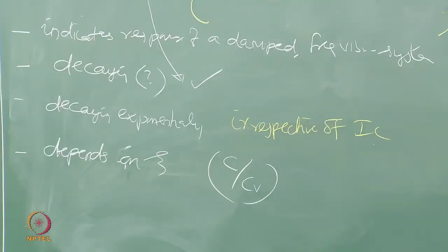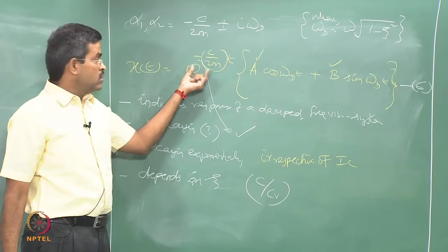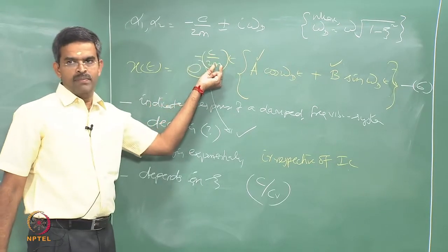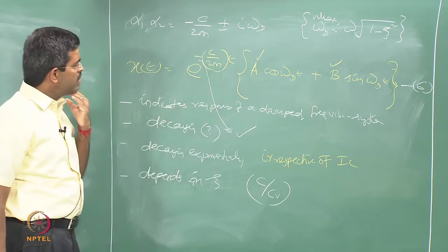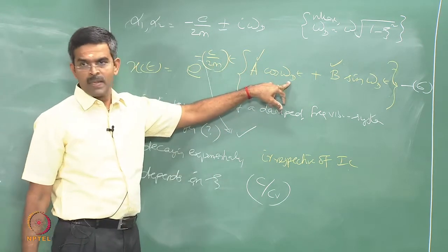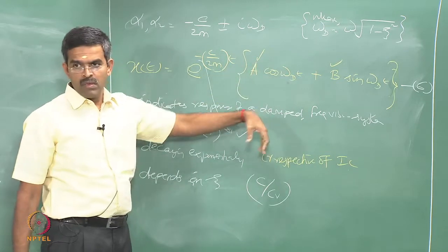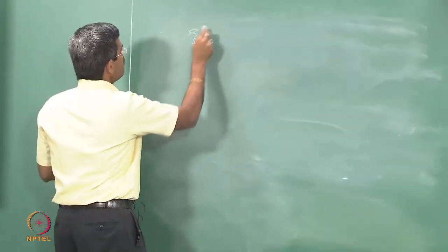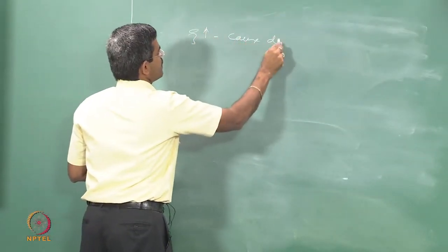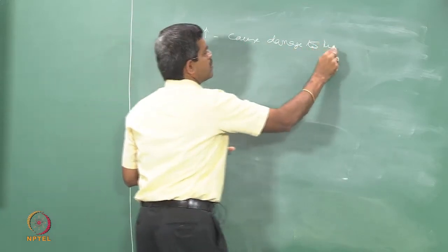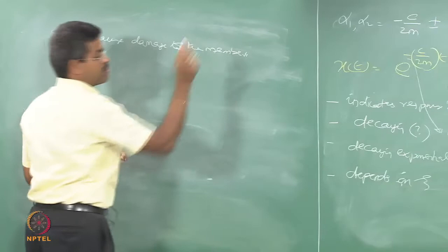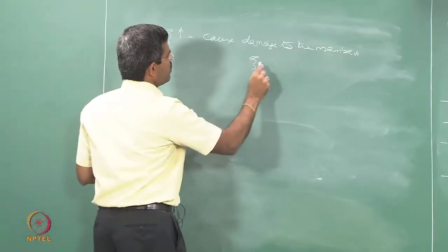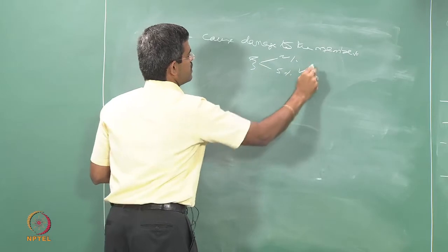Friends, there are two ways to bring down the response. One, the exponential decay, which is related to the damping coefficient and the mass of the system. The second is to give a very high damping, and still it will come down. The second option is not preferred in offshore structures, because damping of high value will cause damage. Therefore, a lower value of 2%, 5% is preferred.